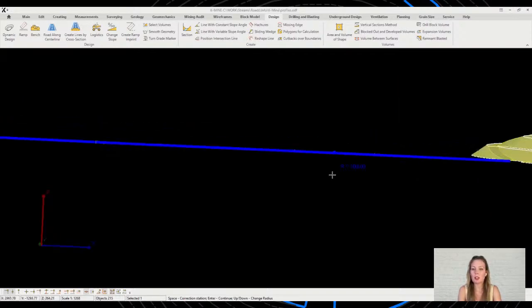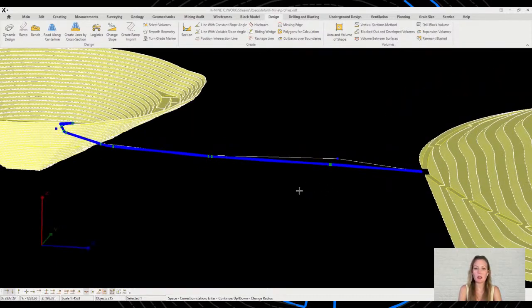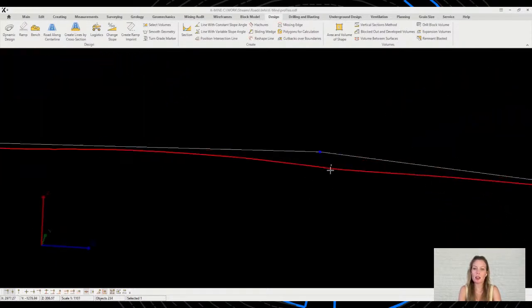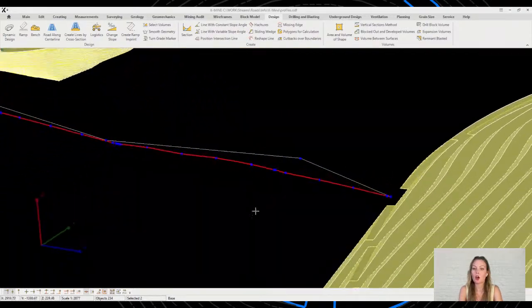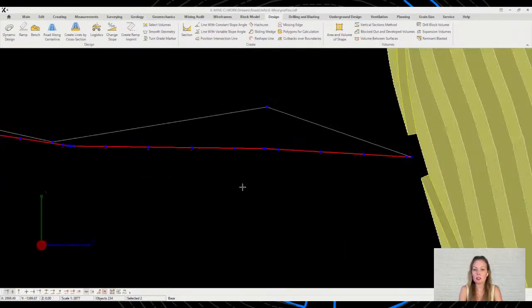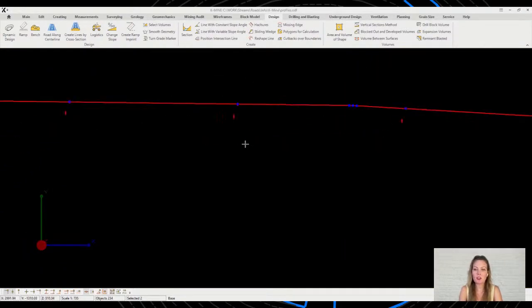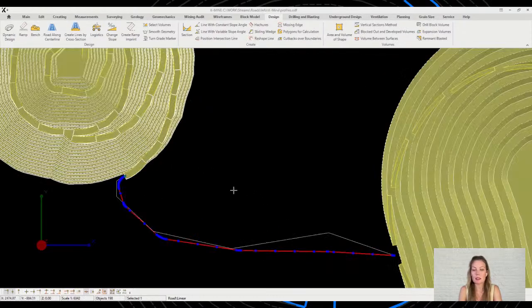After confirming the changes, we return to the dynamic construction stage, and by pressing the enter button, the desired center line will be created. Also, if we added the necessary settings, we would receive band radii, a detailed report, coordinates of points, and other information.